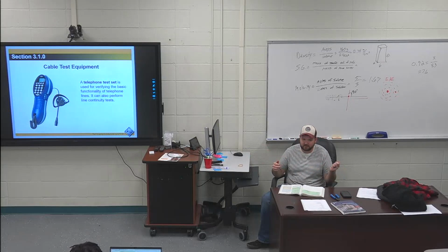So on one side, somebody takes those 10 conductors, strips 2 of them back and connects those 2 together. On the other end, somebody takes a multimeter in resistance mode and goes through all the wires and sees which 2 are connected. And then those 2 wires are identified. You can also go to ground if you have a good ground, and you can test each one to ground and see which one it is.